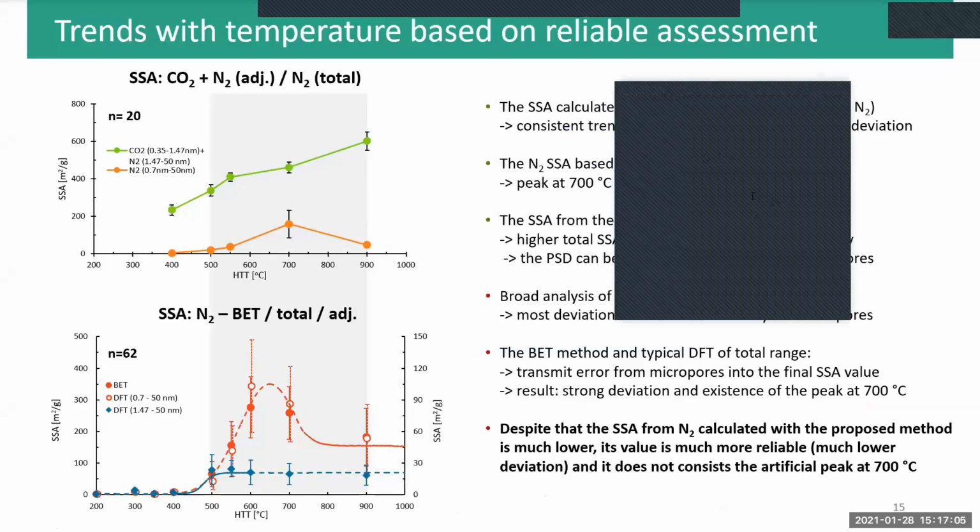The degassing temperature that you used, can you share it with us? We used a degassing temperature of 180 degrees, and we degassed for 24 hours prior to the measurement. Close to the recommended range, right? I think Sigmund recommended 200 degrees Celsius to get stable readings. Yes, in general, the temperature should be high enough to remove all the adsorbed compounds like moisture or gases.